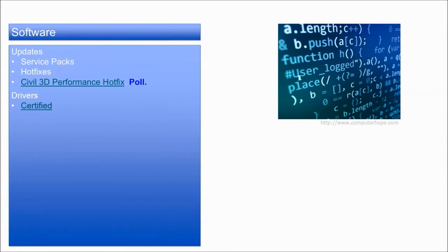Okay, drivers. Make sure your drivers, if you have a certified graphics card, certified on the Autodesk.com website, they certify drivers as well. So make sure you're using the driver that Autodesk has certified.